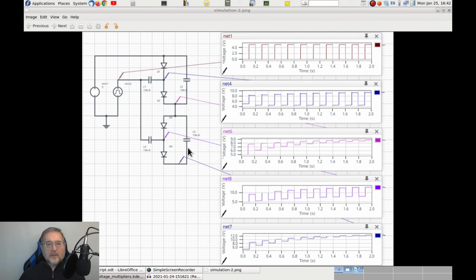The fourth diagram comes from the connection between the two diodes on the second stage. If you compare it with the diagram obtained from the same point of the first stage, you'll see that they are quite similar. This time, however, because we are powering this second stage with the output of the first stage, the voltage goes up to a higher value, and in doing so, it spends a little more time for the upper side of the wave to reach the final voltage. And finally, the last diagram represents the output at the second stage. This one too is similar to the one at the output of the first stage, which is the third diagram. However, the final voltage in this diagram is 3 times the voltage of the power supply.